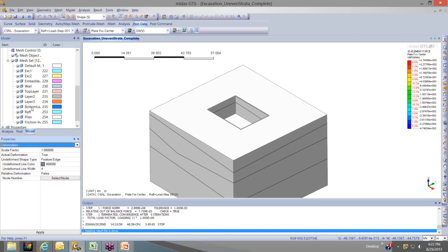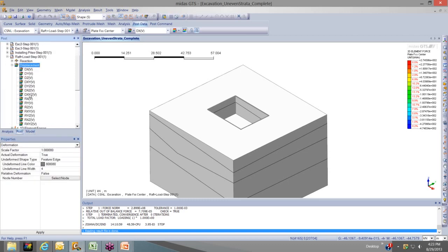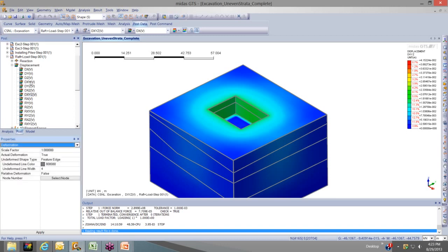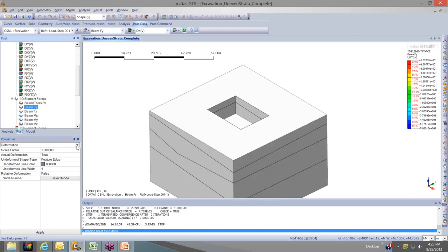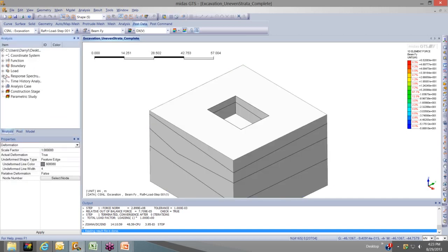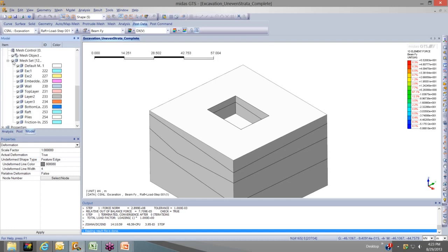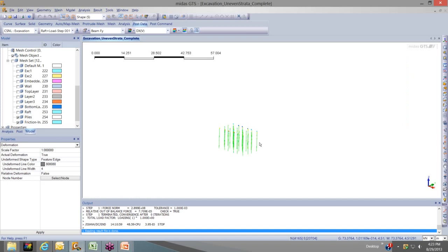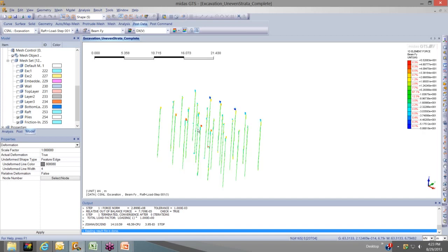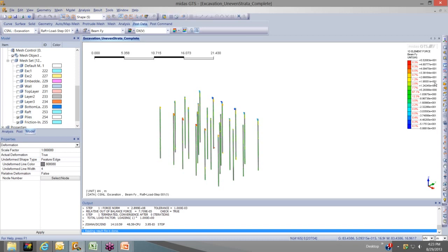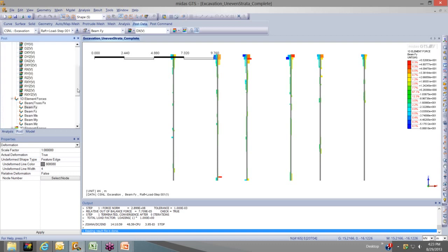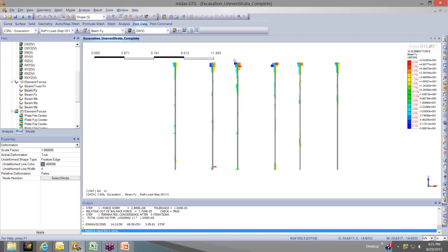And let me make a quick change here. Okay, so for example, say you want to see your 1D results for your piles. I'll go to the 2D strains later. So turn everything off except for your piles, then go back here, and let's take a look at the side view. Then go back to your post cases. Go to 1D element forces. And as you can see,